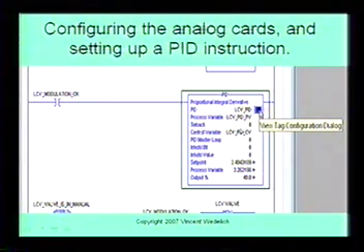Again, I said tieback is 0, so I'm not doing this manually. I don't use that feature. You can certainly use it, though, whatever you feel comfortable with. The control variable here is the level control valve PID control variable. PID master loop is 0, and hold bit is 0, and hold value is 0. Set point here says 2.484, right? 3109. And you can't change these values, right? You can't manipulate these. These are the results.